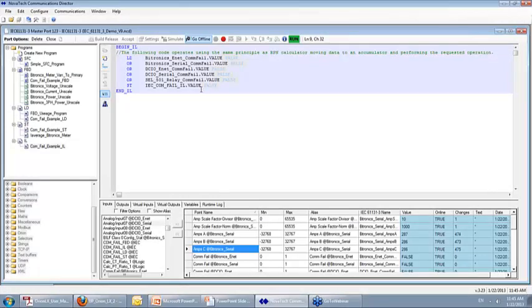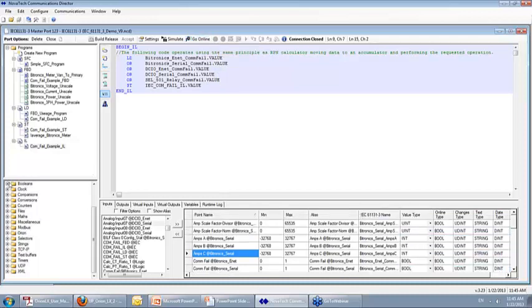Instruction list programming is similar to that which one would see if they had used an old microprocessor, such as a Z80, or perhaps a Hewlett-Packard calculator with reverse Polish notation, where one would load a constant into an accumulator, then type in a value and a function for which one would execute an instruction. Once the instruction is executed, the resultant value would be placed in the accumulator. Within the instruction list, we would again write our program from the available functions in our programming environment.